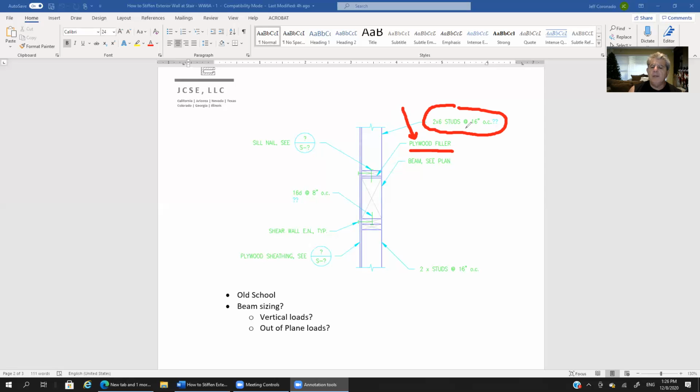But the point is, we need that little filler, because if you do the math of how this wall assembly looks, where the diaphragm does occur versus where there's an opening, you'll see what happens: the double top plate stays at a constant elevation throughout the entire length of the wall. The same is true for this sill plate.